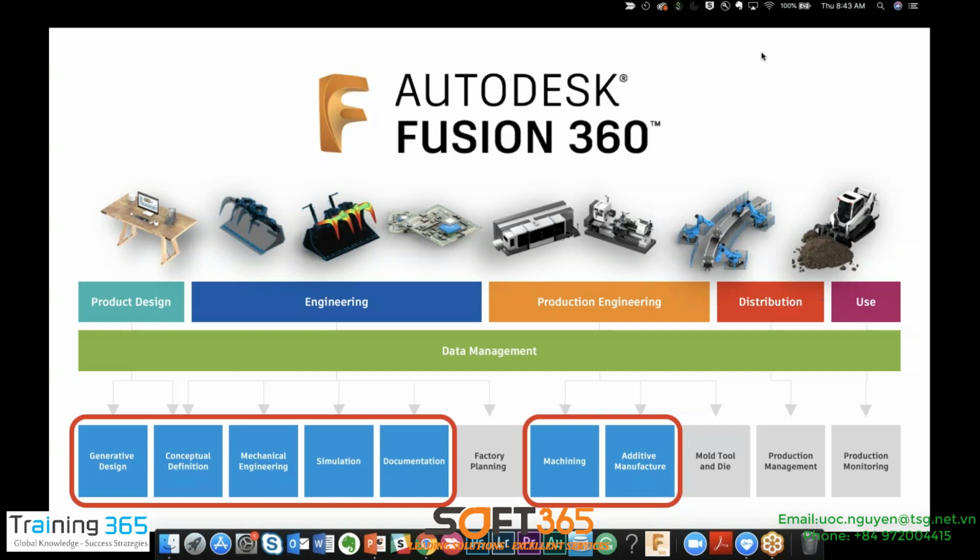With generative design, you can not only get an unrestricted model, whatever the software can generate, which is what we normally see with topology optimization, but it also understands if you're doing an additive process. For example, if you're doing metal additive printing, it will output a model in 3 different directions.